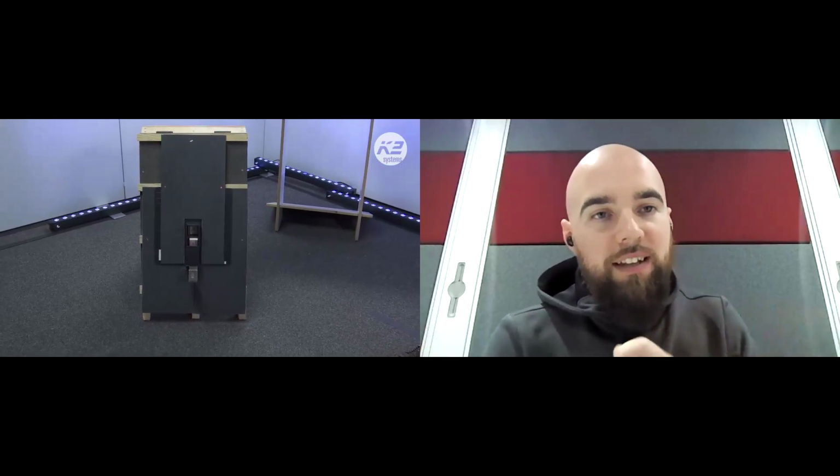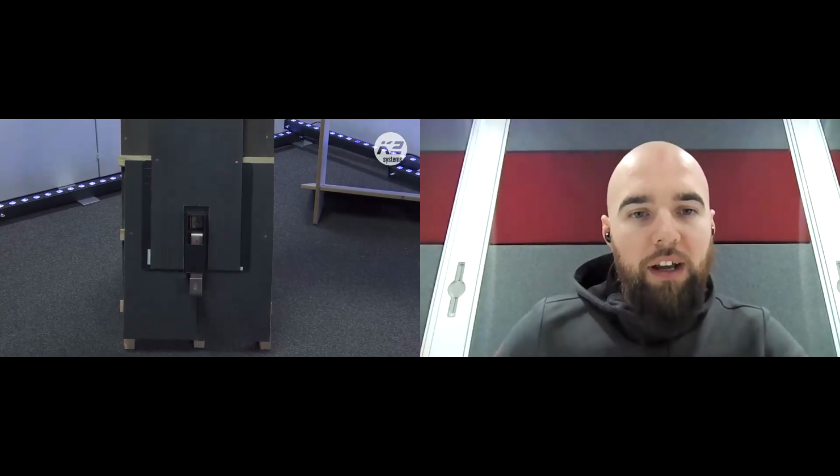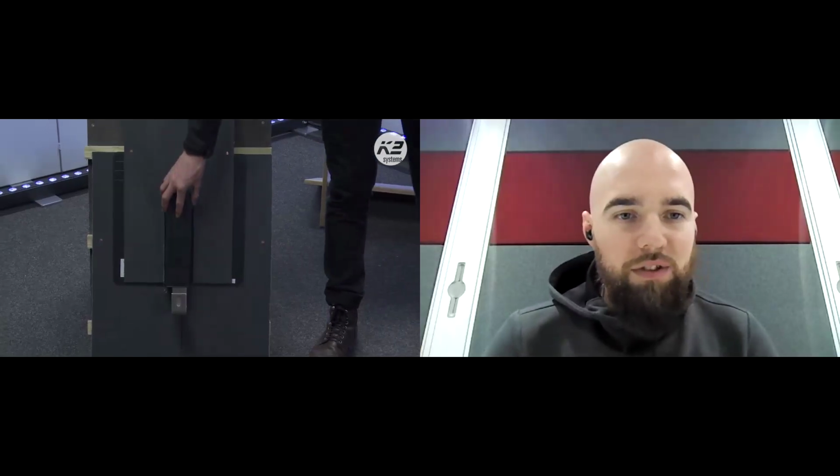It comes with a metal cut-in square that you can slide under the slate, and it enables you to cut the slate in situ. So once you've done that, you can just slide the metal sheet out, and it enables you to fix a hook directly into the rafter below. And then it's just a case of slightly lifting up that upper slate and sliding the Genius Roof Solutions speed flash up under. Yeah, as you can see there. So that will just slide into the cutout, and all done without having to remove the slate tile, which I'm sure a lot of installers will enjoy to hear.